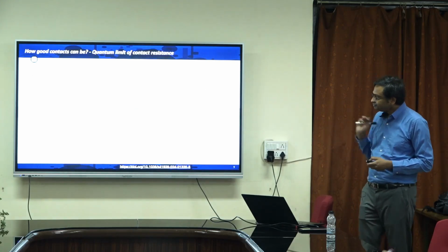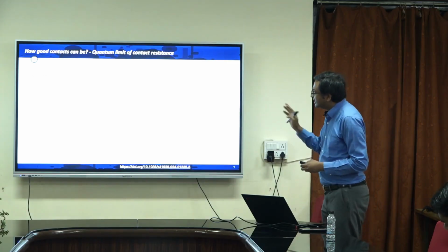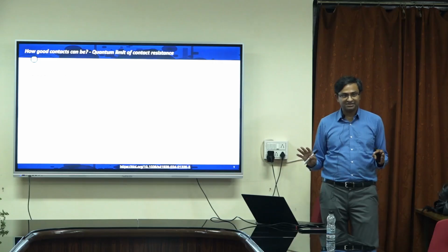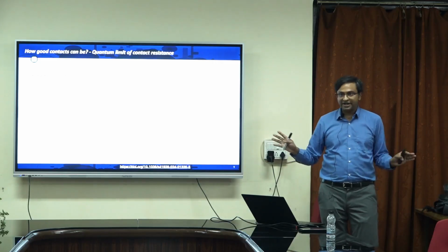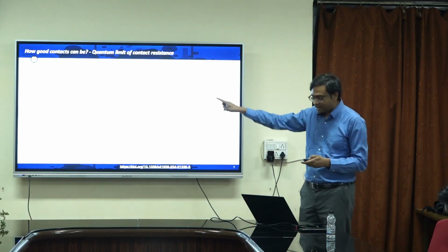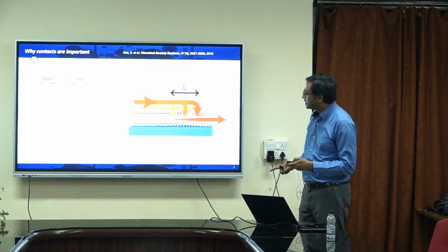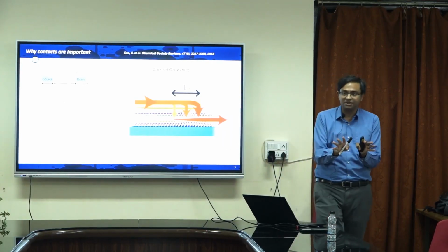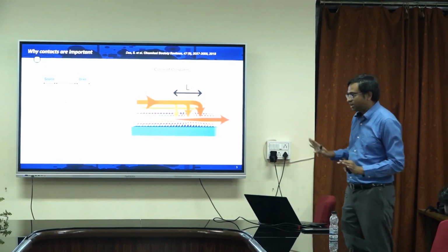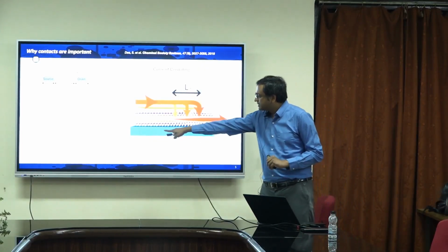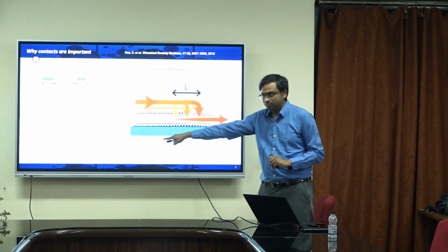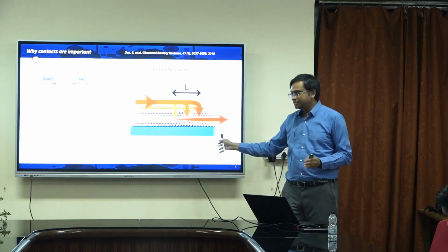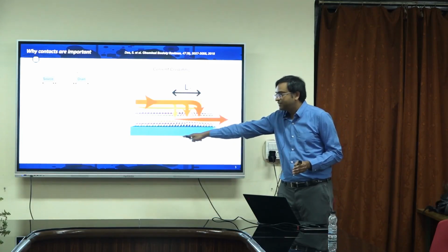Now let's switch gears and ask this question: fundamentally, how low can the contact resistance be? There was this term RC0 in the beginning. We understand that there is a certain length-scale dependence: as I make the contact smaller, the resistance is going to be higher. We cannot rescue ourselves from that. But then there is this prefactor RC0. So the only way for me to reduce the contact resistance is to reduce that RC0, because I cannot get rid of this functional dependence.